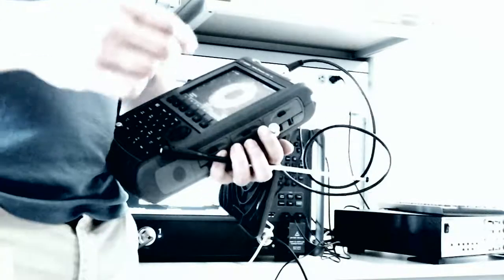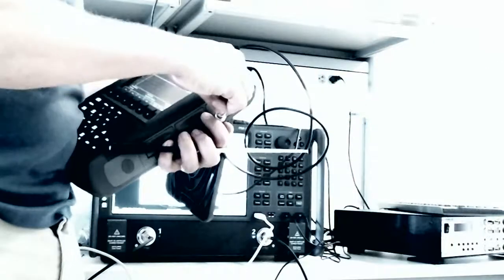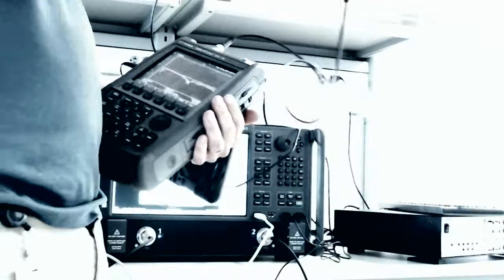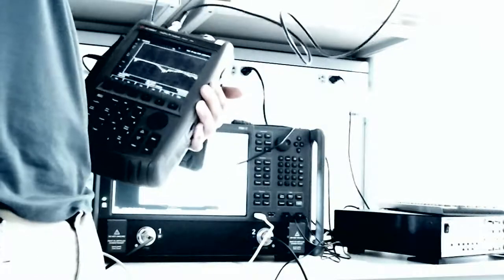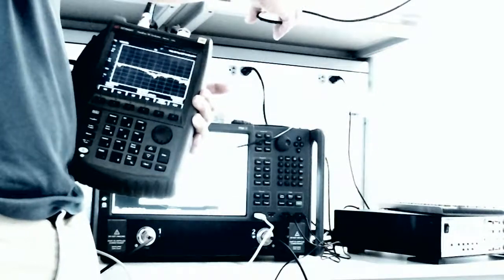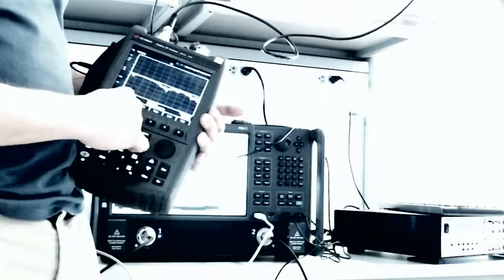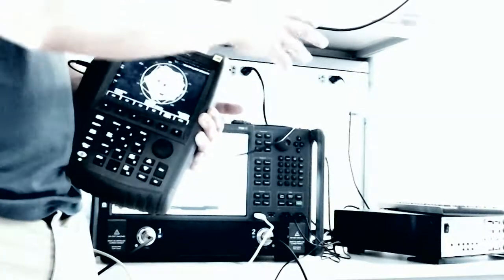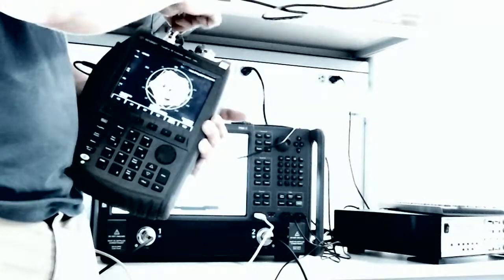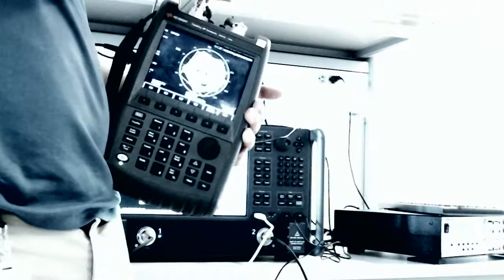Okay, good. Perfect. Does this work? Yeah, absolutely. So let's do line mount here. If I take a look at this, and maybe you want to hold this, as I bend this cable, I'm seeing a little bit of response difference, and that's in magnitude format. But let me go back to the full Smith chart, and based on what I do here, even just moving this thing, I'm getting a lot of difference on that Smith chart.